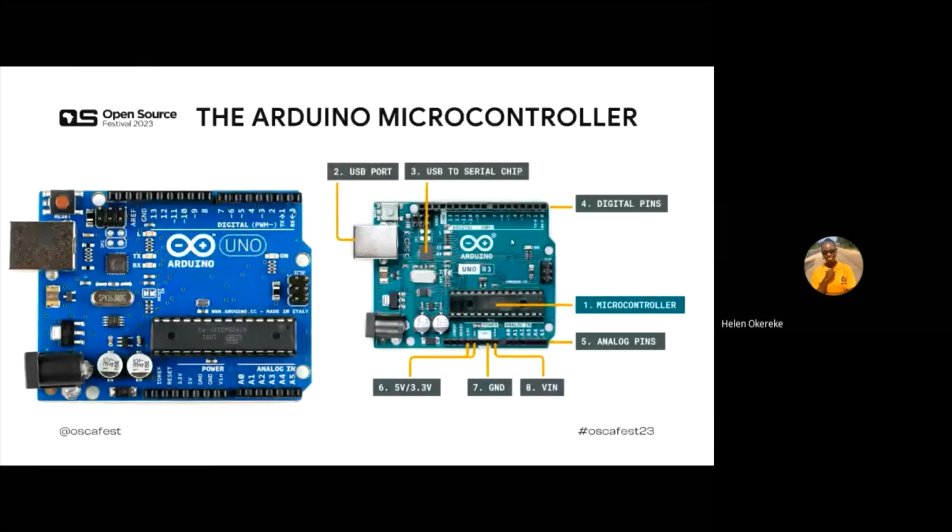For example, if I'm trying to automate 15 bulbs, each of these bulbs has minus and plus, and all these minus and plus must be connected to this Arduino so that the Arduino can control it. But we only have a few GND. Two are here, and there's another one here. Yes, 3 GND on the whole Arduino microcontroller. There are only 3 ground, only 3 minus pins.